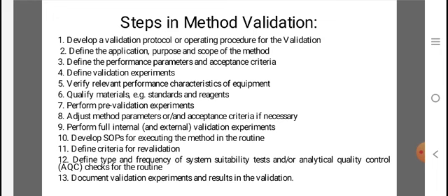Perform full internal validation experiments. Develop SOPs for executing the method in the routine. Define criteria for revalidation. Define the type and frequency of system suitability tests and/or analytical quality control checks for the routine. Document validation experiments and results in the validation report.